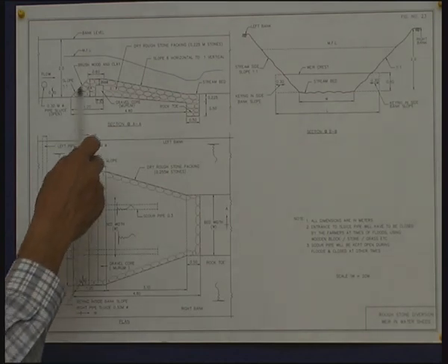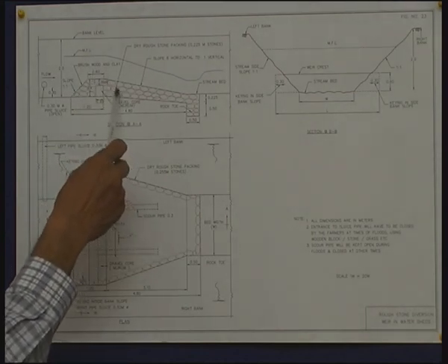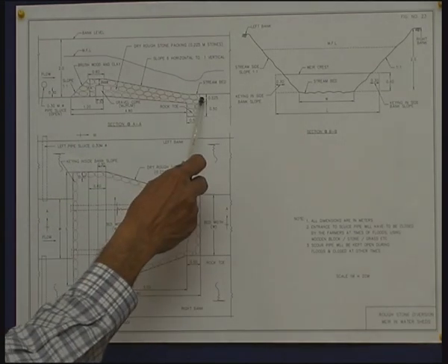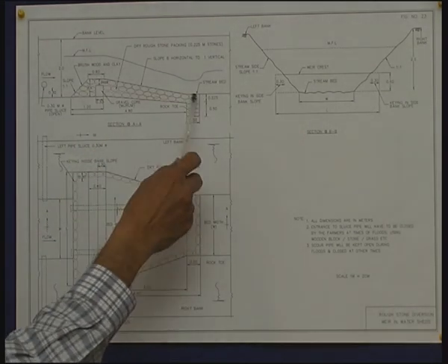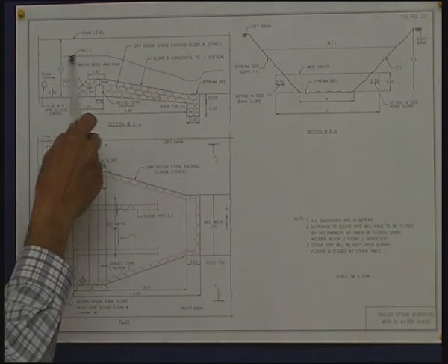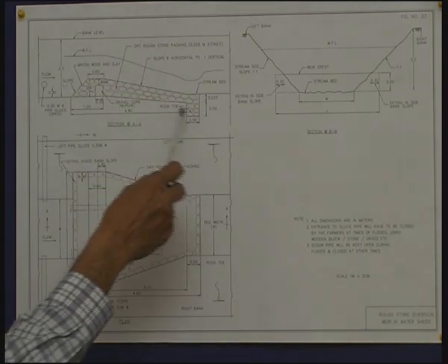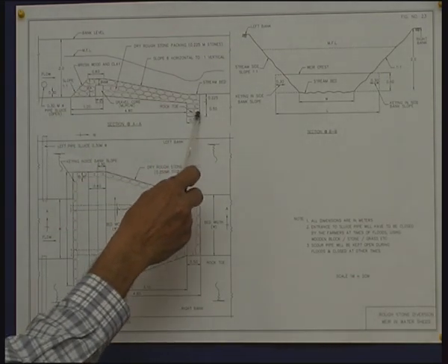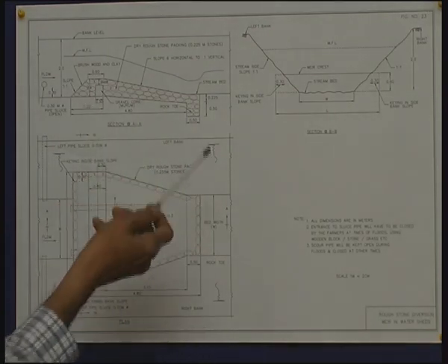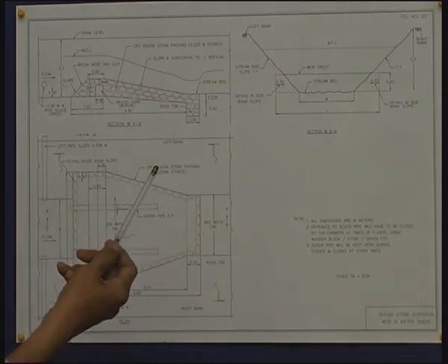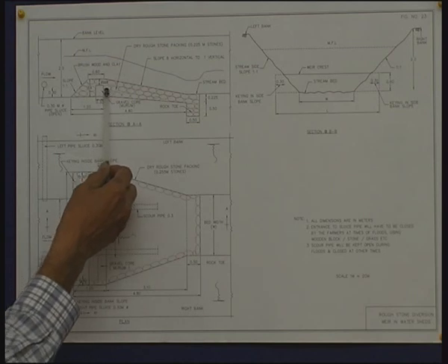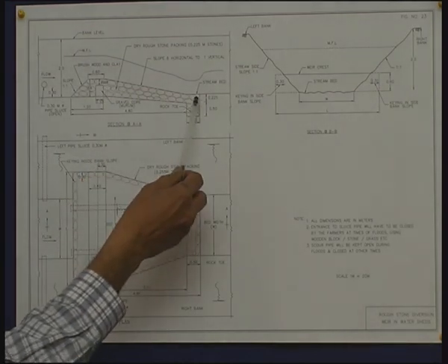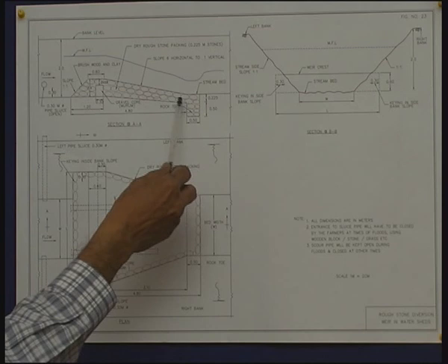That is, instead of constructing like this, we have a lengthy apron which is stable enough under the flood flow conditions, and also provide for a toe. So, the engineering interventions of the modern technology is to have an apron, sloping apron, and a rock toe.